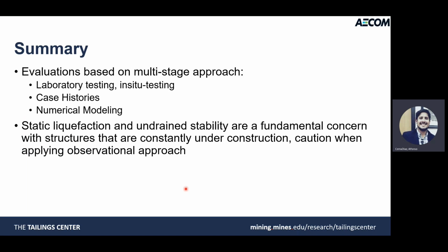So as a summary, I have the following. The evaluations are based on a multi-stage approach. You have to look at your laboratory testing and your in situ testing. You have to look at your case histories, if you have those, to really evaluate your numerical modeling, right? Because you really want to have confidence that the constitutive models you use in your dynamic deformation analysis are calibrated with your case histories and with laboratory testing. And that's basically the end goal of these evaluations: to be able to use these calibrated models to analyze unforeseen scenarios, or different dam heights that may happen 10 or 20 years from now.